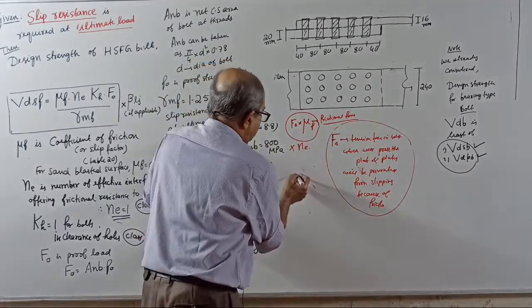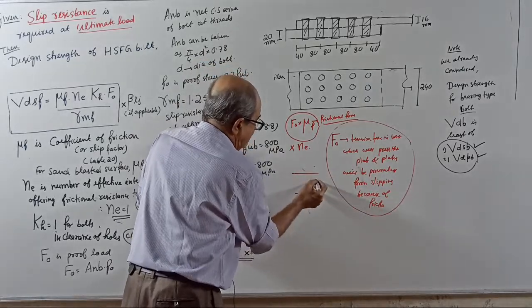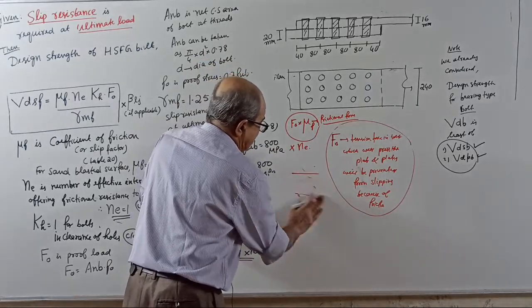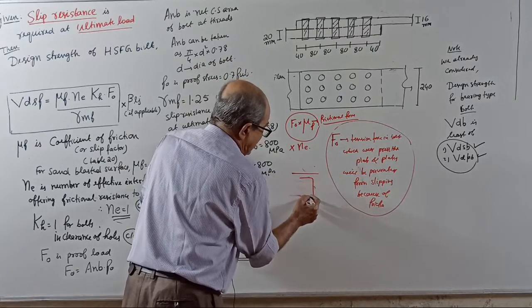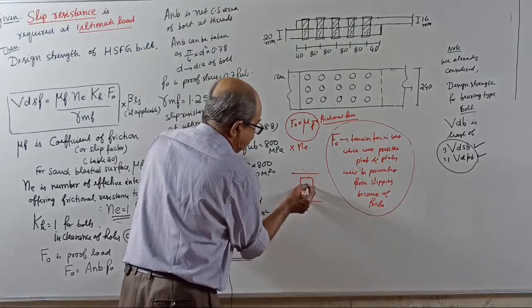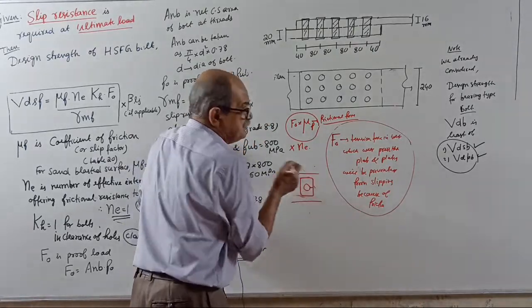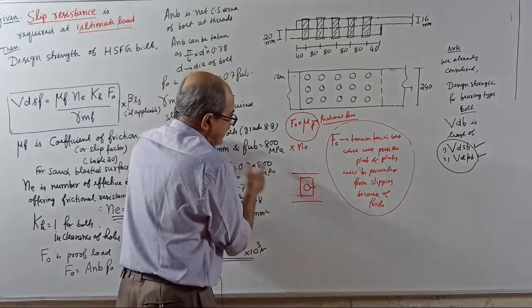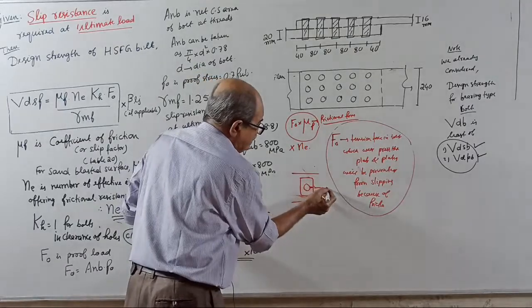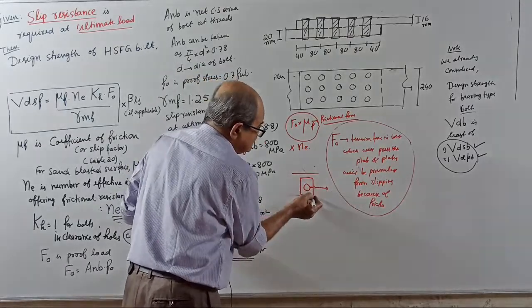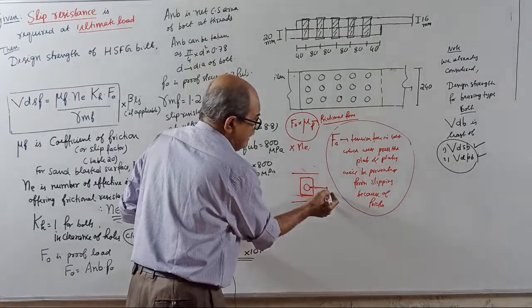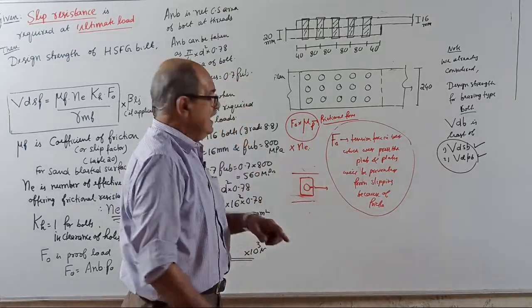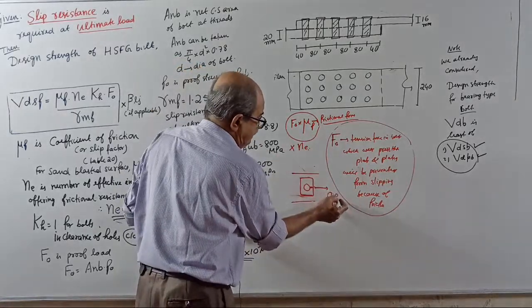But in case of some oversize slot, this way, where more space is there, then this is not good. Here the slot force is in the direction of the smaller side. They want to reduce the strength by 15%. That is a correction factor of 0.85.